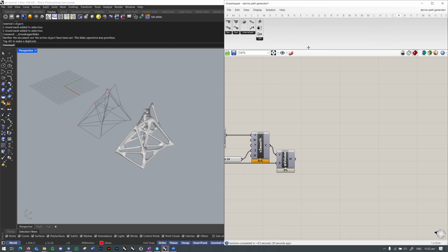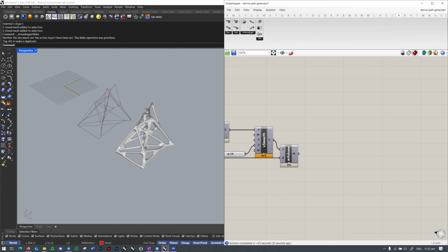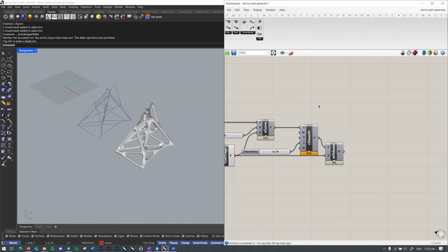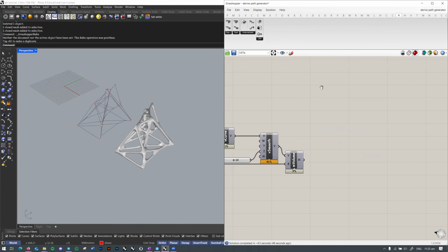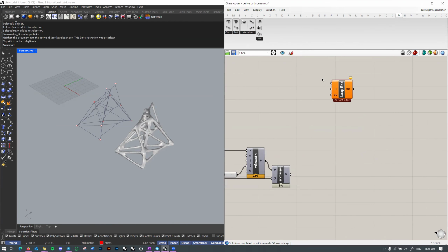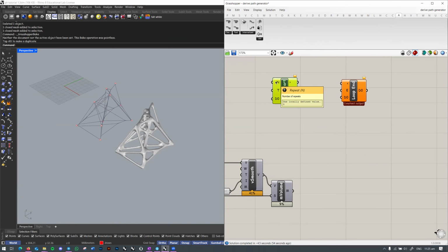Yeah. I even think of Anemone, which is not necessarily a geometry-centric plugin, but a workflow-process-centric plugin. So I have loop ends and loop starts here, because Grasshopper doesn't allow looping, but with Anemone you can create loops where you have a loop start and a loop end, and you can tell it how many iterations to run. And you just keep looping and looping.